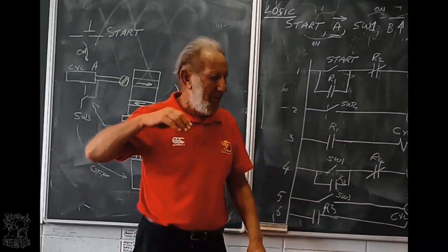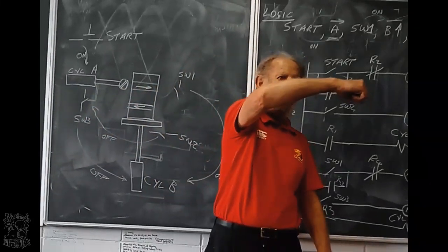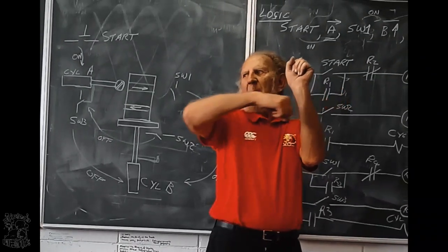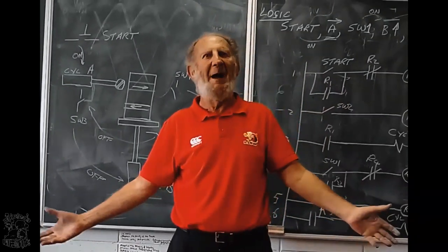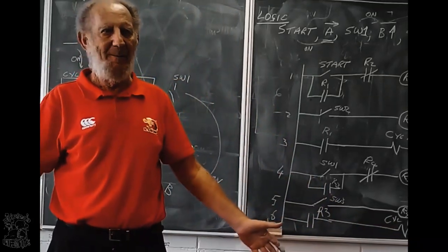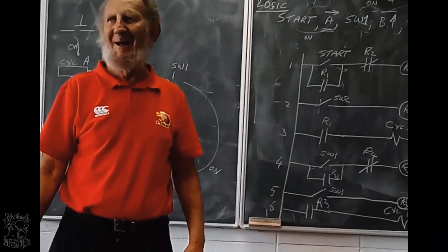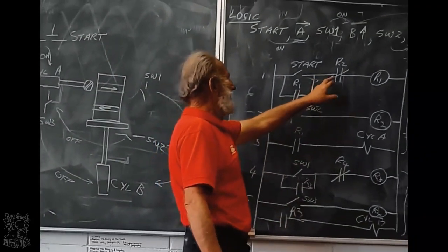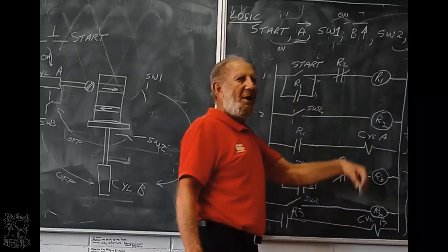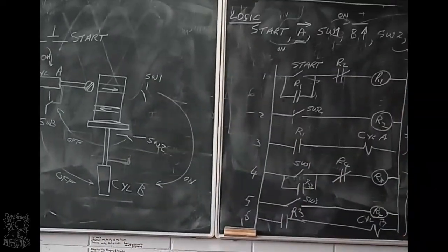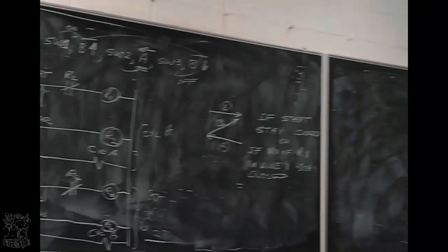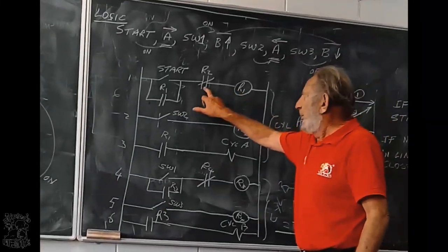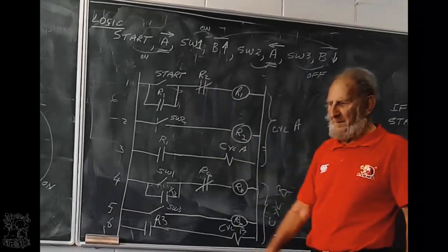So, what will happen is it will cut the first groove, B will move up, and then the machine will stop, because A cannot come back, because it doesn't lose power. Okay? So if that stays closed, it will cut the first groove, B will move up, and then the machine stops.